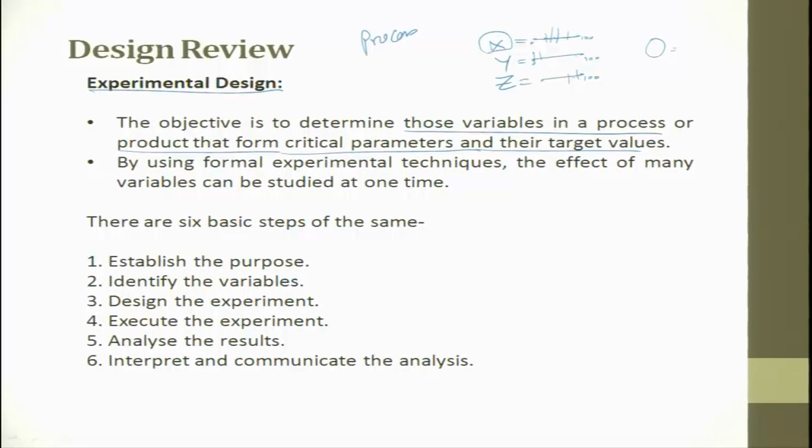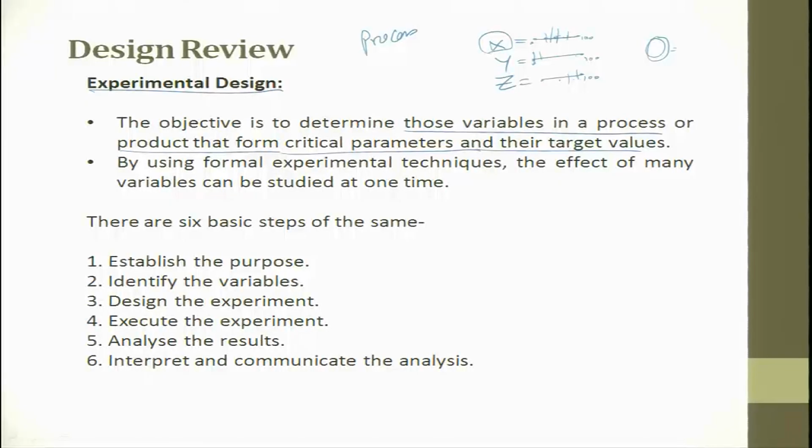So, with minimum experiments, rather than doing continuously all points, we do at discrete points, and then we try to find out which is the significant parameter and what is the optimum parameter in each, such that you get the best target out of it. The target can be higher the better, lower the better, or the mean the better. Okay. So, that is how you structuredly do the experiments and figure out the best parameter so that you get the good output.